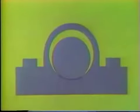With this process, a thin layer or film of lubricant is distributed and maintained between the bearing and the shaft during rotation. The space between the bearing and the shaft is filled with oil. When the shaft is at rest, most of the oil is squeezed out between the bearing and the shaft by the weight of the shaft. When this happens, the bearing and shaft are in metal-to-metal contact.